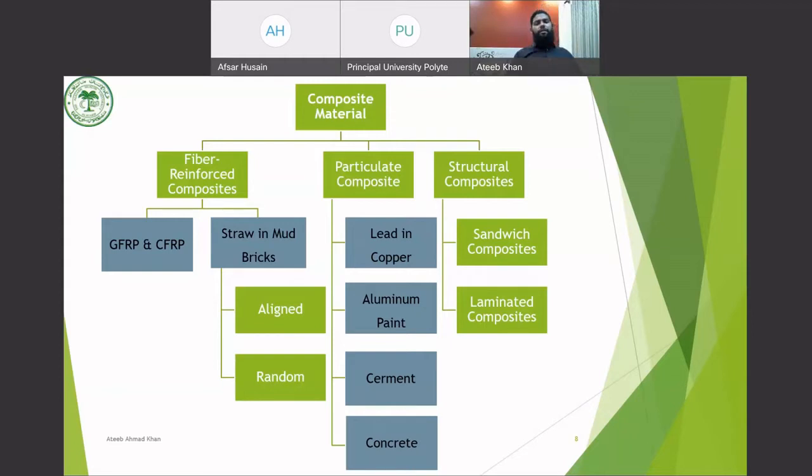Dr. Balachandran, you are absolutely right. Concrete is a type of composite material, but I have basically compared concrete and reinforced concrete because this is a very common example and everybody is aware of concrete and reinforced concrete. And just by using the fibrous type of composite, you can see that the strength is significantly increasing. As I told you, the tensile strength of concrete is near about 2 to 5 megapascal, whereas for fibre reinforced concrete, the strength is near about 100 megapascal. So you can see that almost 50 to 60 times the strength is increasing.